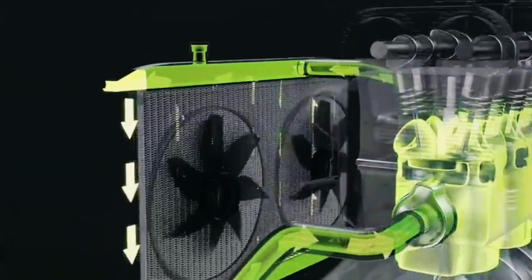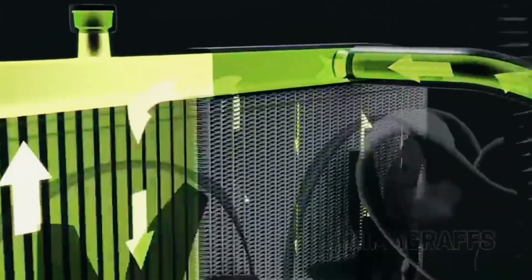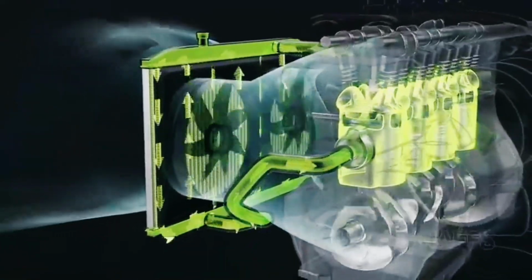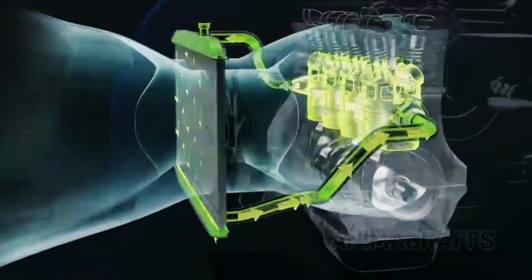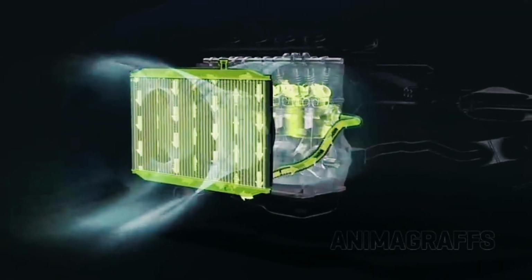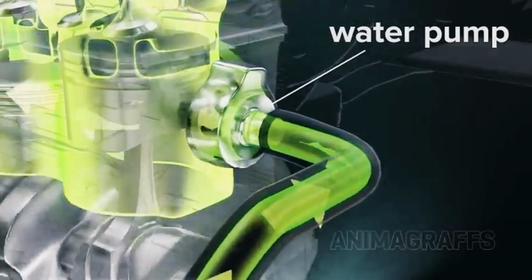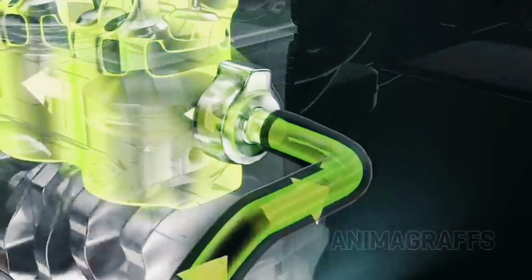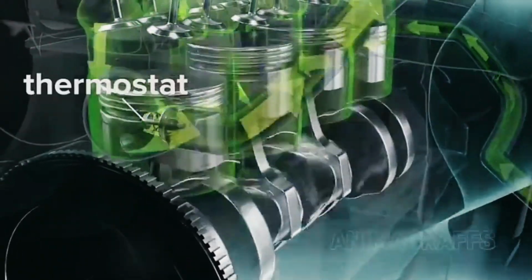After cooling hot engine parts, coolant circulates through the radiator. The radiator has a network of small tubes and fins. Coolant passes through these channels, while air, pulled in by the radiator fan, blows by the tubes, cooling the hot liquid for recirculation. A water pump keeps the coolant system flowing and properly pressurized. A thermostat regulates coolant temperature by either routing coolant back through the engine or to the radiator for further cooling.